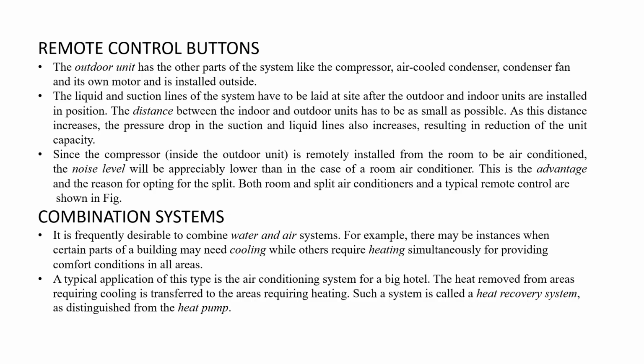The liquid and suction lines of the system have to be laid at the site after the outdoor and indoor units are installed in a particular position. The distance between the outdoor and the indoor unit has to be as small as possible. If this distance is more, it takes a longer time for the process. As the distance increases, the pressure drops in the suction and liquid lines also increase, resulting in a reduction in the unit capacity. This is the process.